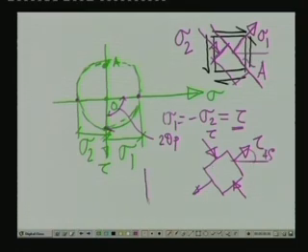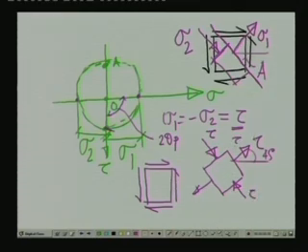So, either we represent that at a point in a stressed body, the stresses are purely in the form of shear or in the form of normal stresses having magnitude as that of shear, which is tensile tau in the maximum normal stress direction and the compressive tau in the other normal direction. So, this is the state of pure shear.